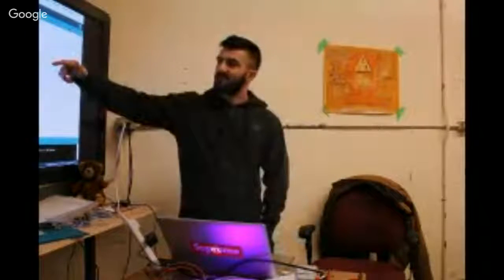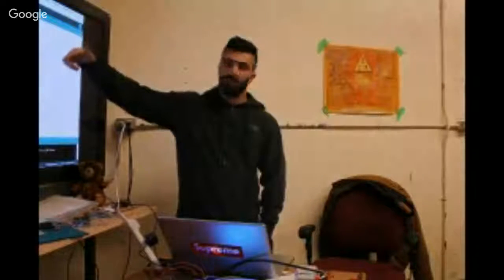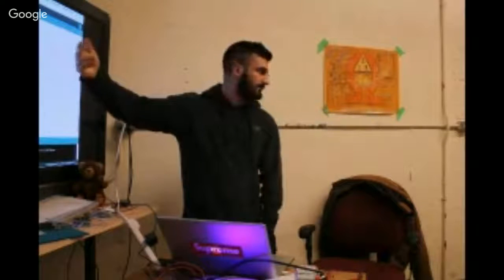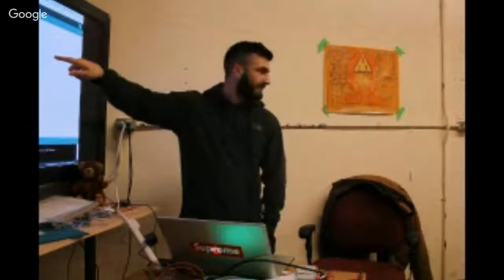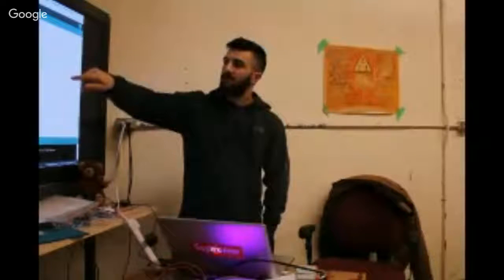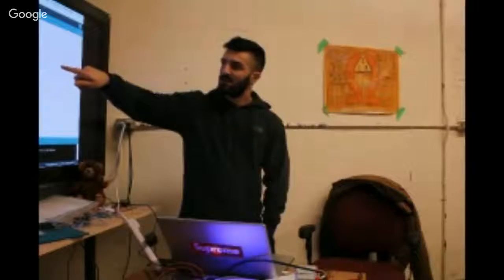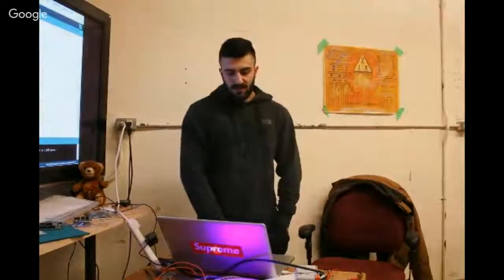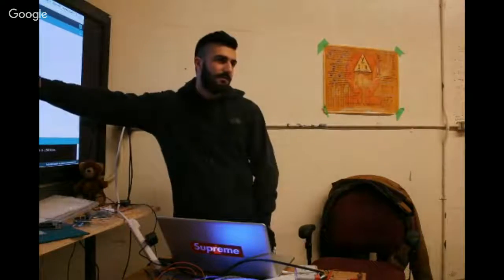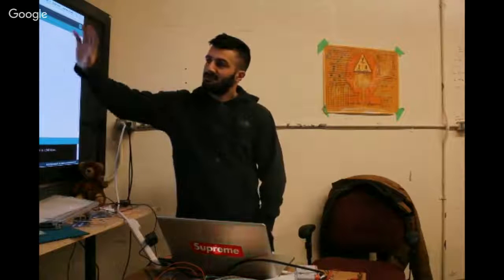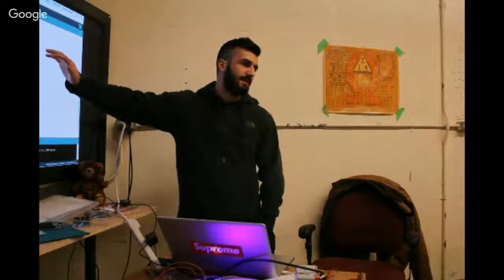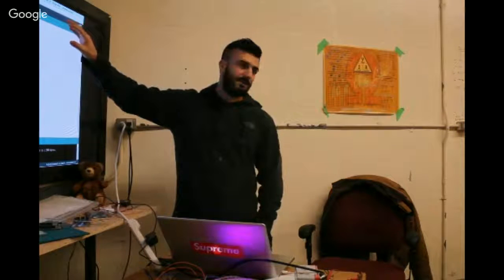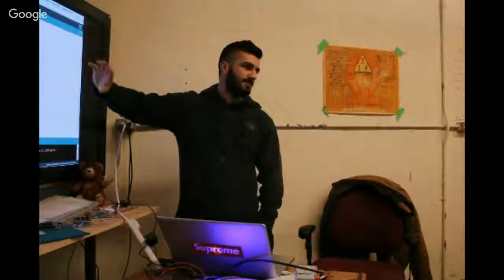Then we go into the next if statement. If we don't go into the first one, the next one is, is the button pressed? So if button equals 1 or true, we'll turn the fan off. That's why it says fan state equals 0. We'll turn the button state on, and that's commented out. It shouldn't be. Then we'll set the timer for 10 minutes for the button. So now the fan is off and it's going to be off for 10 minutes. So those are our 2 if statements: if there's motion and no button pressed, and if the button is pressed, then we do 2 different things.